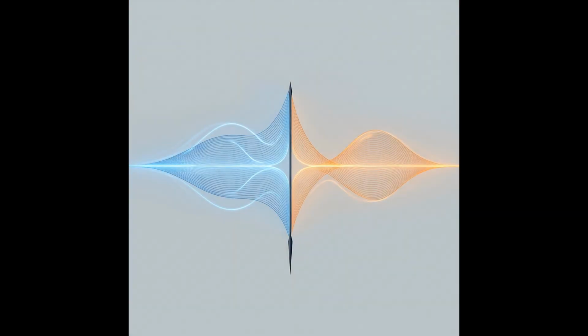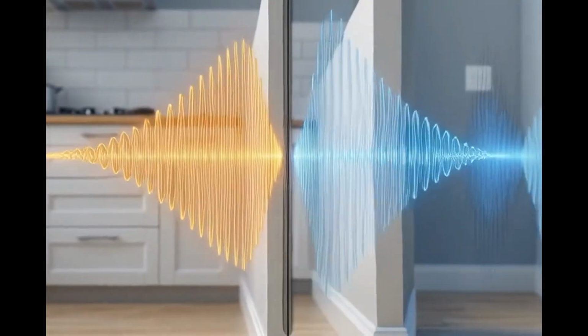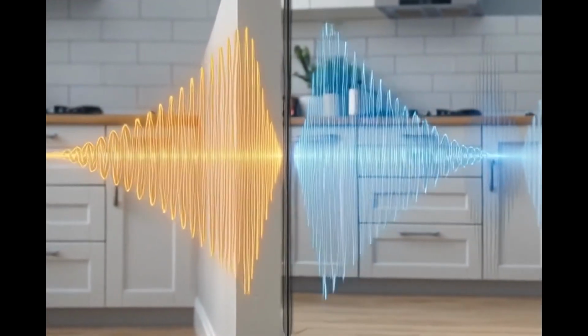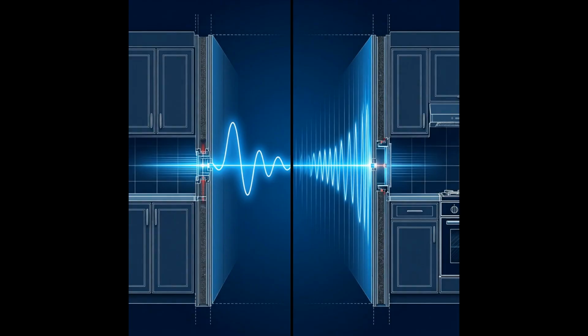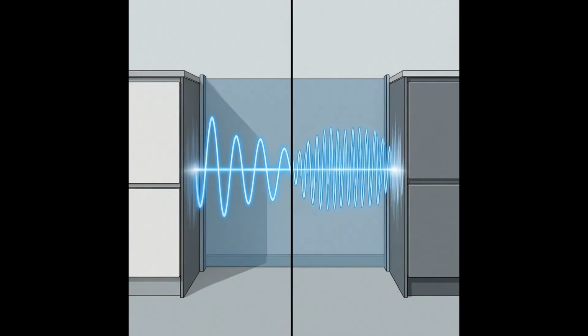The geometry of your kitchen creates specific dead zones because different radio frequencies interact with physical barriers in fundamentally distinct ways. We must examine the inverse relationship between frequency and wavelength to understand why 2.4 GHz signals often outperform 5 GHz bands inside enclosed spaces. Lower frequency waves possess longer wavelengths, which allows them to diffract around obstacles like walls and appliances more effectively than shorter high-frequency waves. For instance, a 2.4 GHz signal behaves like water flowing smoothly over a rock in a stream, maintaining coherence after passing through drywall or metal surfaces.